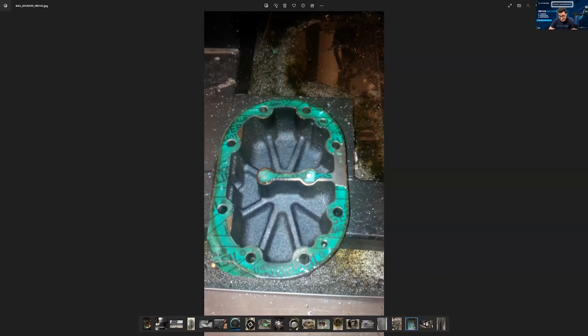Because there was a very thin film of this stuff in the air, especially when you were near any of these large GM plants like we had, or the manufacturing plants for brakes and all that stuff, and a lot of machine shops. You never thought about that kind of stuff. But the condenser would look fairly clean. But boy, when you started cleaning it, you noticed the difference, and you could watch that head pressure drop. You noticed the improved flow. It was really kind of amazing.